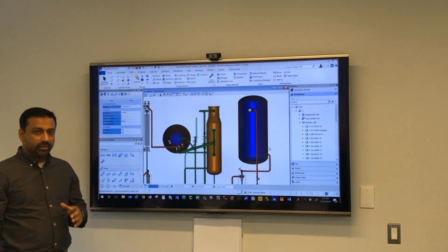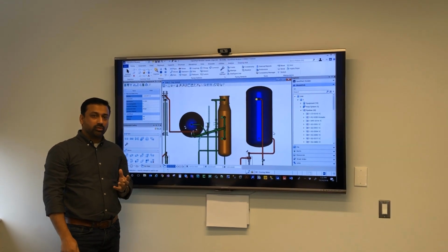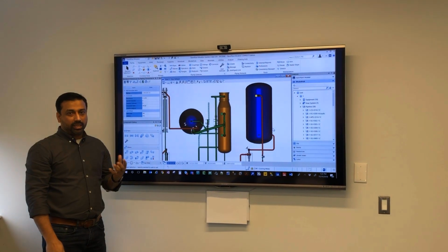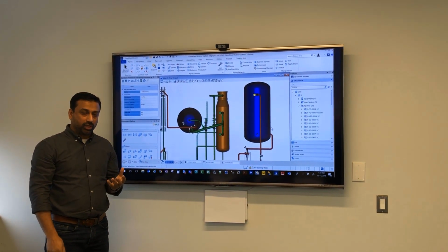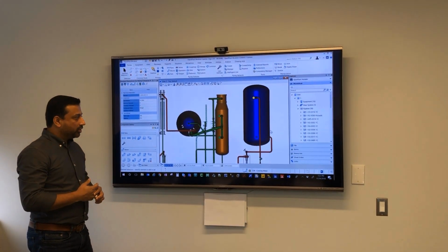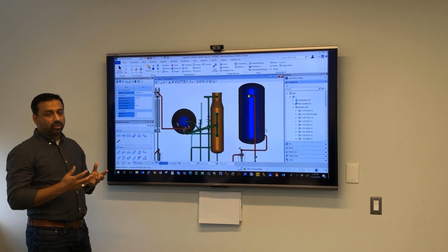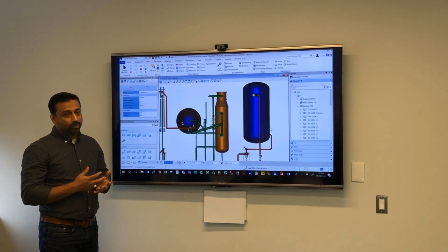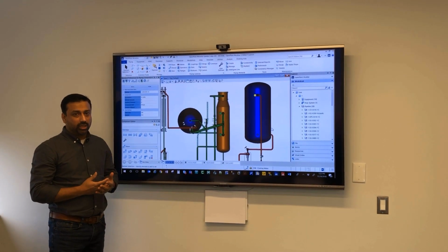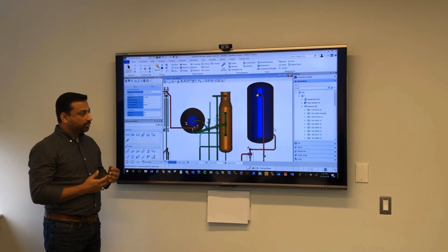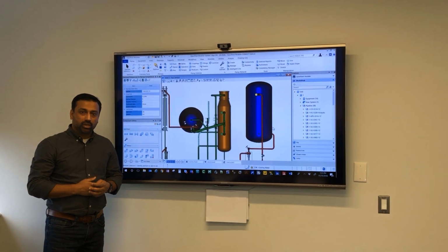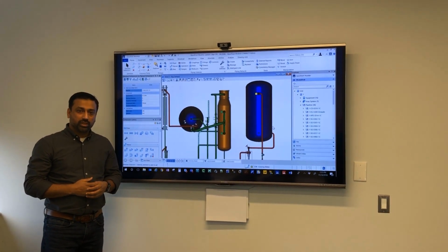So today we learned that dropping a custom equipment geometry retains the EC properties in an envelope, and we can apply that to redefine geometry, totally different geometry, or some updated geometry for custom equipments. So that's a quick way to customize or edit the equipments, especially because the shapes can be different, each equipment is unique. And this quick tip can help you expedite the overall design process. So I hope this was helpful. Thank you for watching this tech tip.